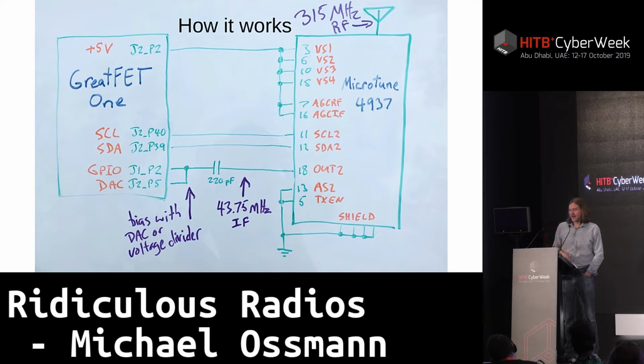And we're sampling that signal with a GPIO pin that we were operating at less than 43 megahertz, which is kind of cool because we were doing a trick that's known as undersampling. We were sampling at a speed that was lower than the frequency we were sampling, and that works just fine, generally, with some limits. But we were also doing another trick called oversampling, and specifically oversampling and decimating. This is the key thing to understand to know how it's possible to build a radio receiver out of a 1-bit sampler, a 1-bit ADC.